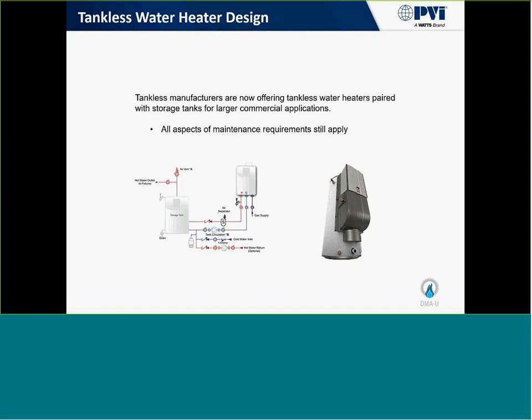But one thing that needs to be said is the maintenance of the tankless water heater would still apply. You're still going to have a very tight flow path going through that heat exchanger, which becomes very prevalent in hard water type applications.